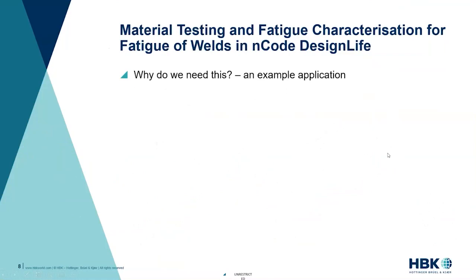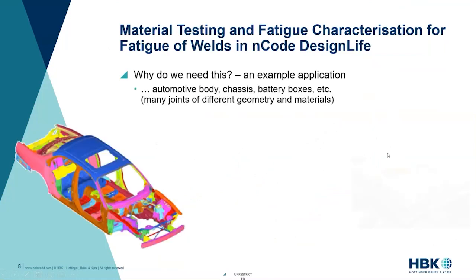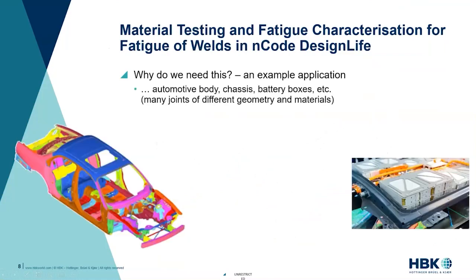Looking a bit more closely at why we need this, for automotive body, chassis and battery structures, there are many welded joints of different geometry and materials. For computer simulation and prediction of durability, we use nCode DesignLife fatigue analysis tools with material fatigue properties, providing a fatigue curve for use in the analysis.